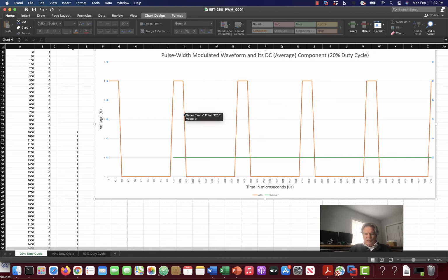And if you can do this fast enough and use good quality MOSFETs, you can make what they call a Class D audio amplifier and produce pretty decent music. I'm sure there are audiophiles who would argue how good it is and that sort of thing, but many subwoofer type drivers, which tend to run at low frequency anyway, use this technique, and you see them in cars and they'll say, well, this is a 1600 watt amplifier, an 800 watt amplifier, and it's a kind of a clamshell type thing of cast aluminum.